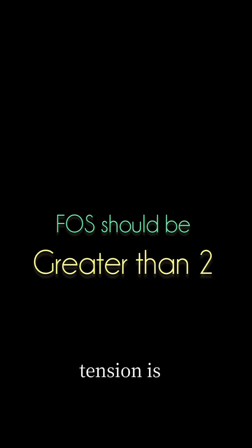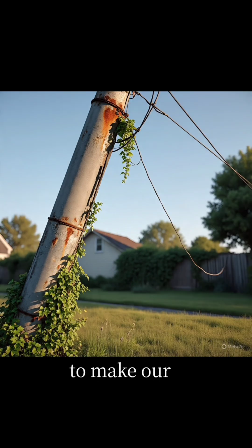If we go through the FOS for cross arm torque, it is about 2.68. For pole base FOS, it is about 2.41. If the value goes below 2, then it is a very dangerous condition. Thus, despite the fact that the FOS for conductor tension is much larger than the other two, we have to keep our pole erect and not tilted. Thanks.